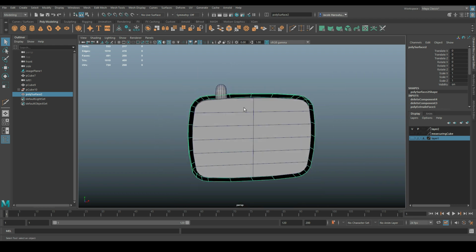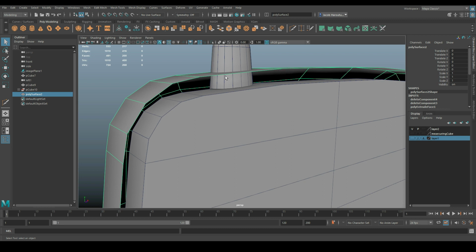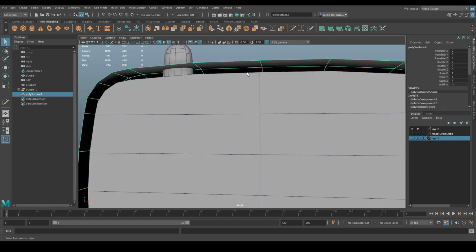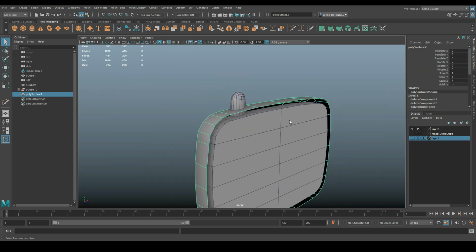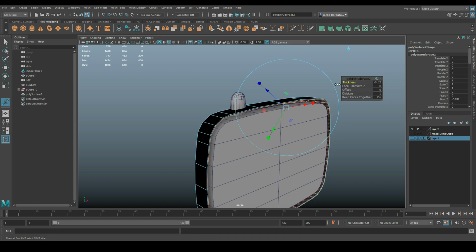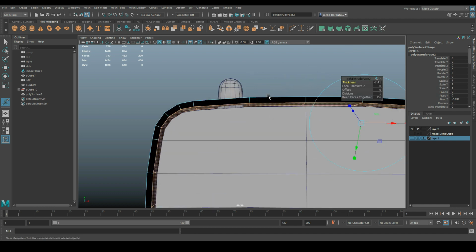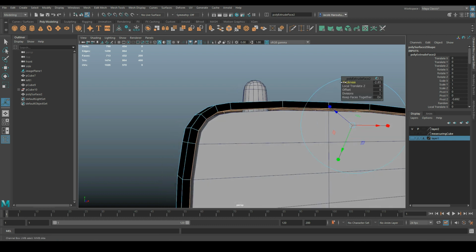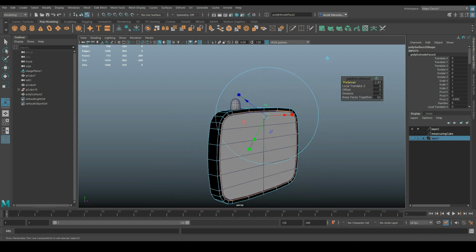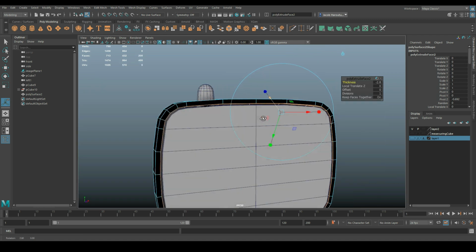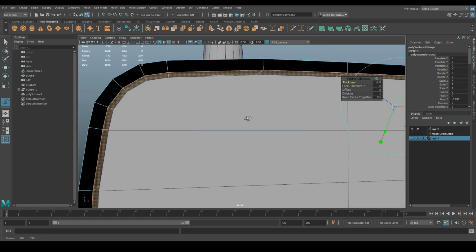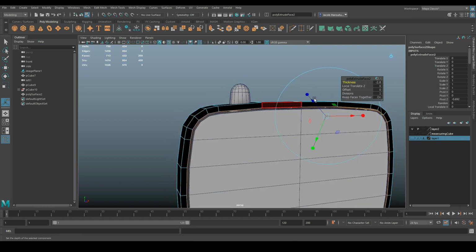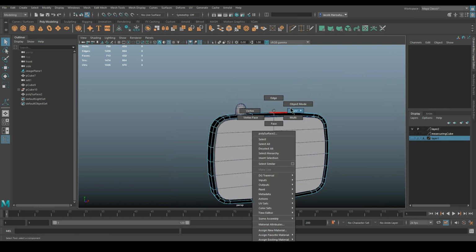And why did I do this? I did this because I'm going to want to now create the thickness of this shell and with a gap in between where the screen's going to go in to the case. So now that I have that shell there, I'm going to go ahead and extrude it again. I'm going to expand the thickness inward and I'm going to give it a pretty big gap there. And that gap, by the way, is tolerance. So that's a pretty big gap. And I just want to make sure that I've accounted for any sort of error that I may have done in my measurements, because I would like to have this done first time around. Okay, that's looking good to me.